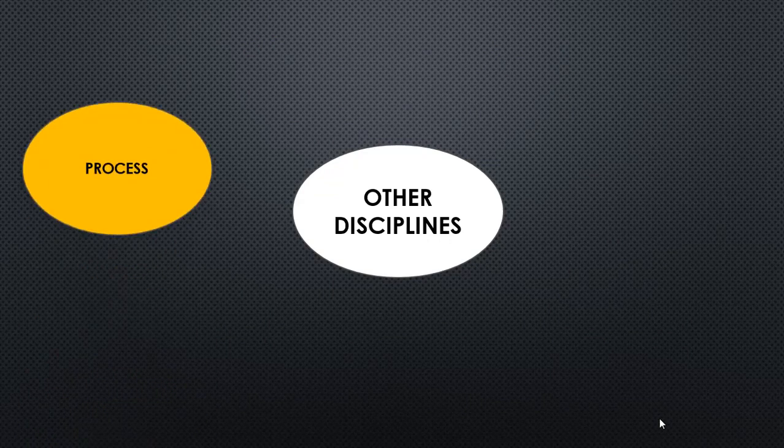Process is a discipline from where we receive primary inputs such as PFD, process flow diagram, P&ID, piping and instrumentation diagram, and line list, which specifies the design temperature, design pressure, operating temperature, operating pressure and density, and also various data sheets of inline items of piping.